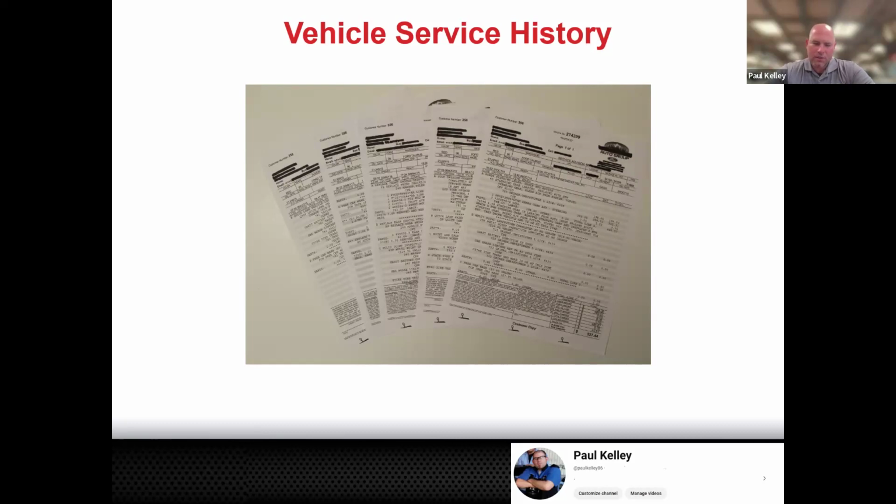But in the case that they forgot, it would come in for AC blows warm. Maybe they had the engine done in the winter, and by the time it's summer, they just realized the AC doesn't work. Or if the AC doesn't work and you notice they did a job recently that might have to do with disconnecting AC lines, you may first want to go right to where those disconnections were and see if the leak happens to be there, right? So if a car comes in, knowing the history can help us pinpoint maybe where to start our diagnosis. Make sense? So consider that.